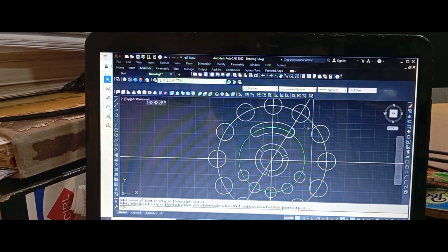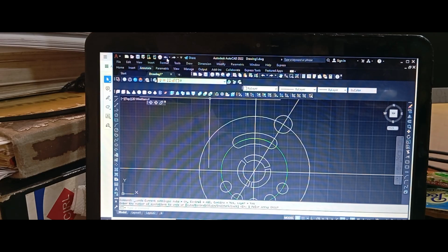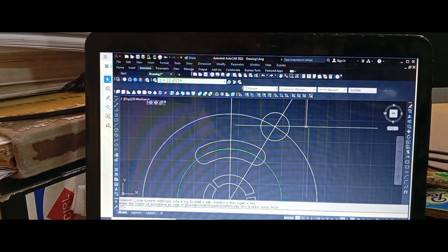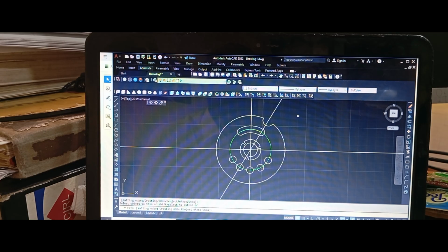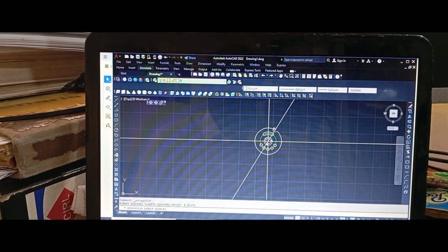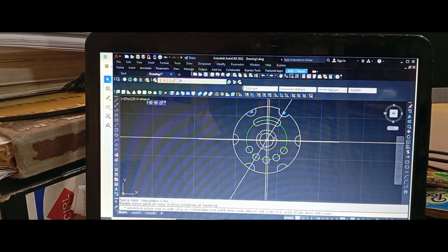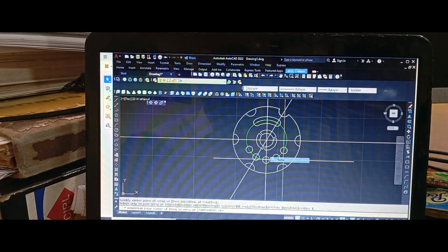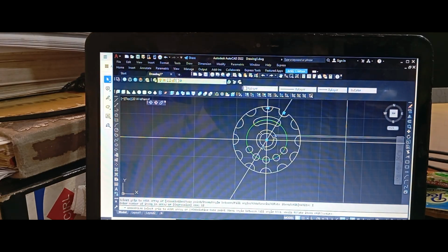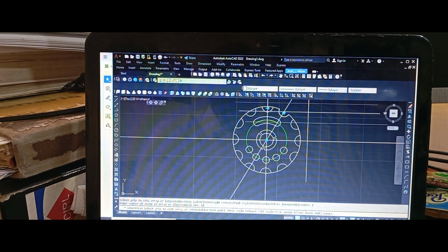The next thing to do is I may not even start with polar. Let me do some trimming from all the shapes, right? Good. So I will now go polar with that shape in place. Click the center line, right click, item 12. If that is in place, I can accept that.